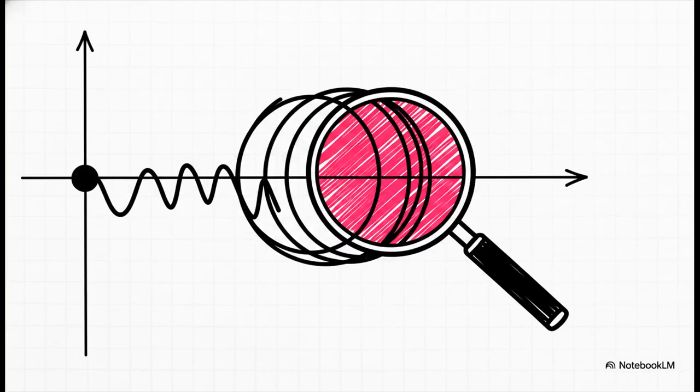That massive mapping spits out a beautifully simple equation, z equals p minus n. It tells us that the number of unstable closed-loop poles, z, equals the number of unstable open-loop poles, p, minus the counterclockwise encirclements, n. If z ends up being anything greater than 0, there's no way around it. Your physical machine is going to go out of control.